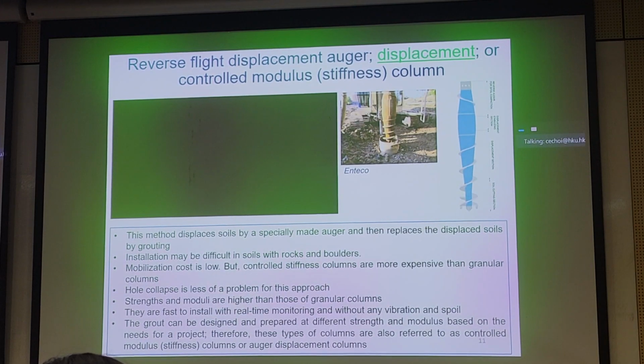And this of course has limitations as well. You're probably looking at maybe 10 to 15 meters in terms of marine deposit depth that you can improve and place some sort of bearing load on top. Some limitations: you're worried again about hole collapse if you don't have casing. High water table, you probably don't want to put too much grout in situations with a high water table.